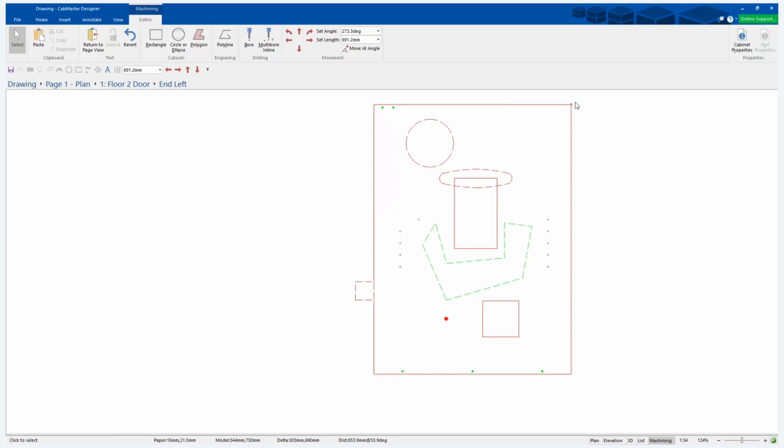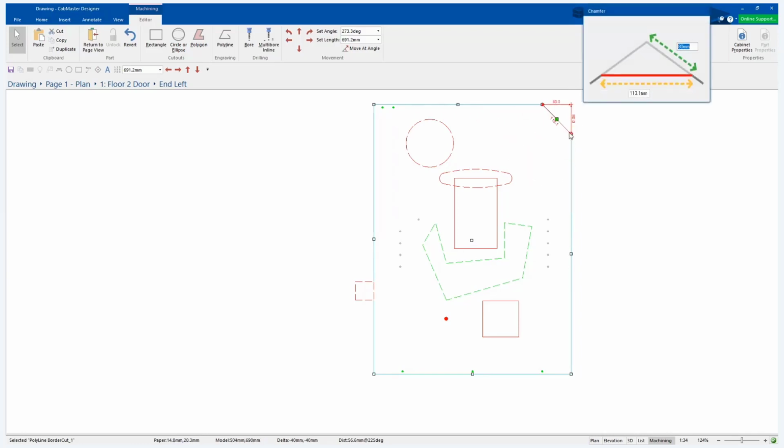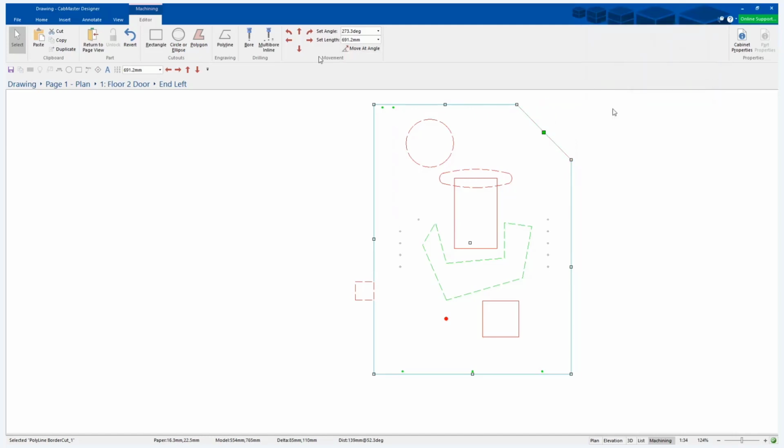The other thing is if you want to chamfer a corner or fillet a corner. Same thing, chamfer a corner, you can literally freehand drag. You do have some default lengths set, which I'll show you in a minute. So you can freehand this, or you can type in up there. You can type in you want it to be 150 mil long. Hit tab. Whenever you type in a number, always hit tab. That's now 150 mil across the diagonal, or let's make it 150 mil long down the side. So it's now 150 mil that way. Hit enter, and it will accept that change.